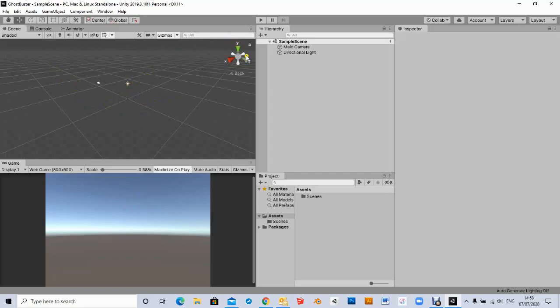The first thing you'll notice is this widget in the corner. Right, this enables you to control how you're looking at your world. Now you can do separate things, like you can pan using the scroll wheel. So if you press the scroll wheel down, we can pan across this world. If you use your right button, you can rotate around. So you've got that eye option there. And as you do that on the right mouse button, you can see the little widget is moving around as well.